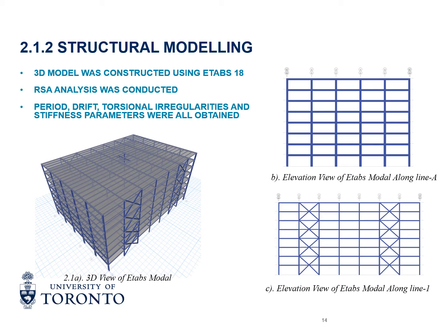This analysis was conducted by restraining the model in one axis and running the modal analysis. This provides us with a period, base shear, and displacement parameters for each direction, x and y. Per code requirements, the base shear provided by ETABS in each direction after each RSA analysis was scaled accordingly until convergence of the period and base shear were obtained in each axis. After obtaining all the necessary parameters after model convergence, the detailed design of each SFRS began.